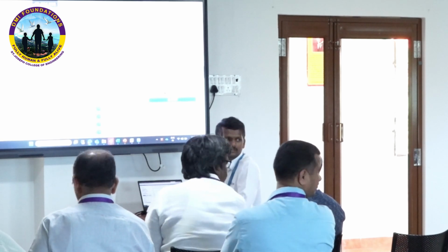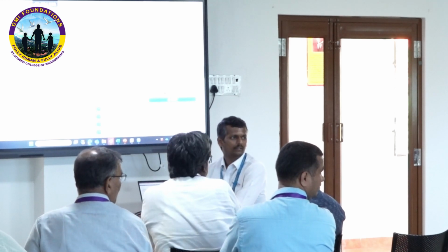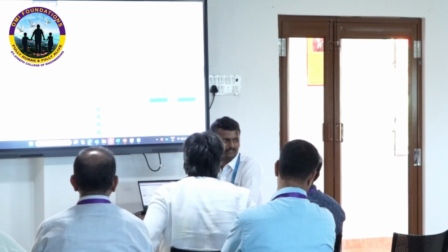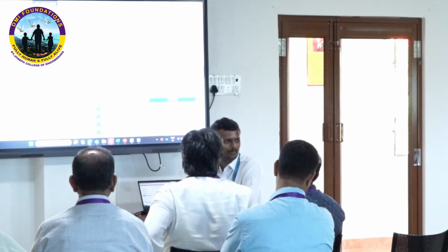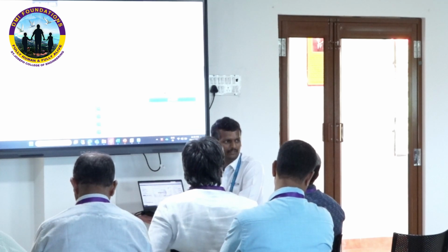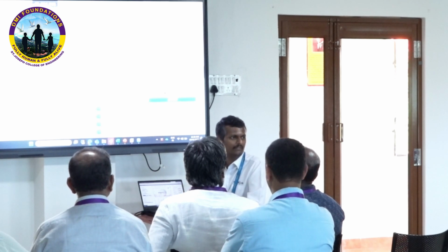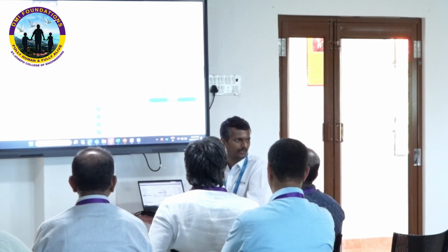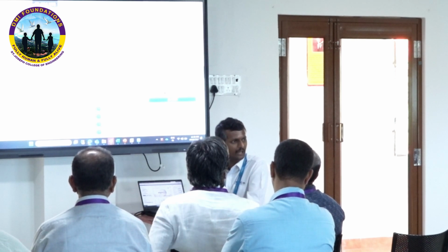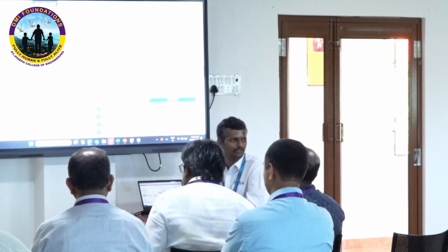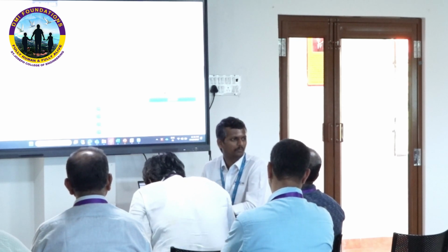So, for a power failure, is it possible to resume? No, sir. We have not activated that option. The reason is, if a power failure happens, the temperature and everything goes down, and it will not have the capacity to hold the part. So when you try to start it again, the print failure will happen. The better thing is not to use that kind of option.